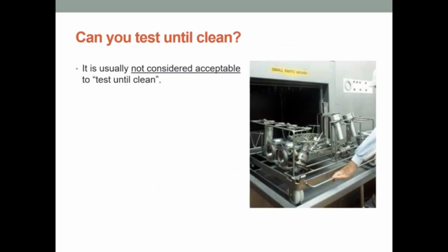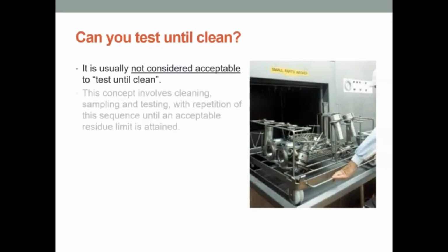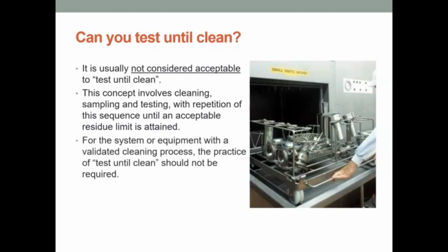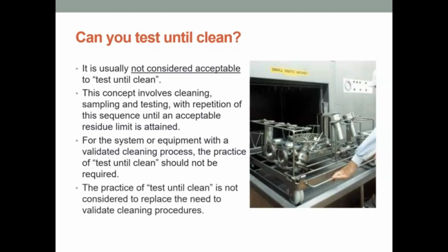It is usually not considered acceptable to test until clean. This concept involves cleaning, sampling and testing with repetition of this sequence until an acceptable residue limit is attained. For the system or equipment with a validated cleaning process, the practice of test until clean shouldn't be required. The practice of test until clean is not considered to replace the need to validate cleaning procedures.